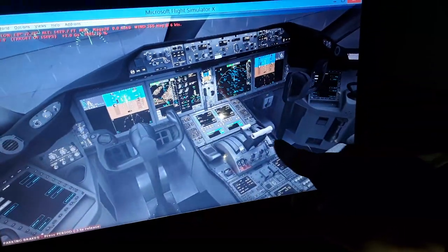We're gonna use, as I told you, the values: takeoff gross weight, the minimum dynamic core position, horizontal trim stabilizer, the fuel on board, the passengers and the cargo. It's gonna calculate the center of gravity. We're gonna input also the flaps for takeoff. We're gonna use 15 degrees of flaps for this flight. You're gonna see I'm gonna use the flap over here. 15 degrees is gonna display over here in the icon. So I will show you how to use also the flaps and the speed brakes.